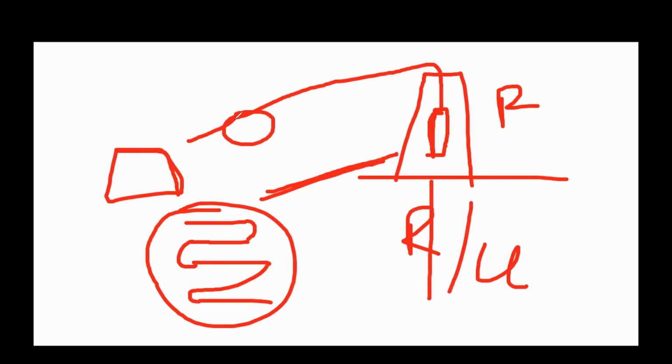Slowly it will be running. At this meter, a depth sensor will be there, a pointer, termed the depth sensor. This depth sensor will tell how many meters of cable went into your wellbore. So like this, they are going to do it.